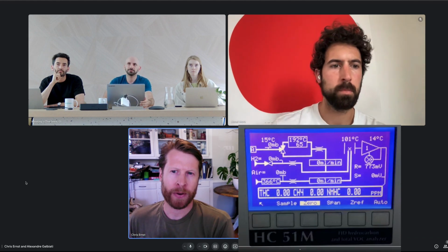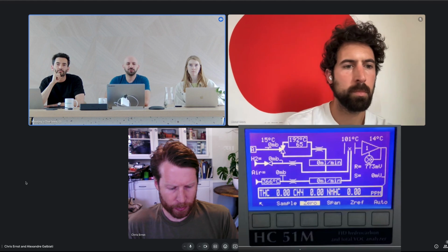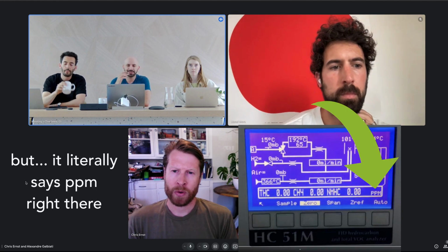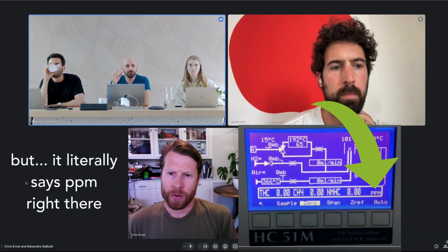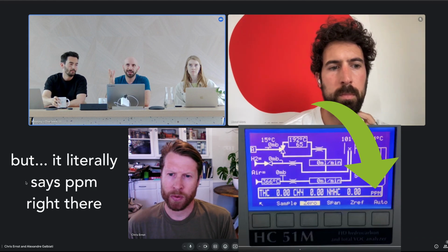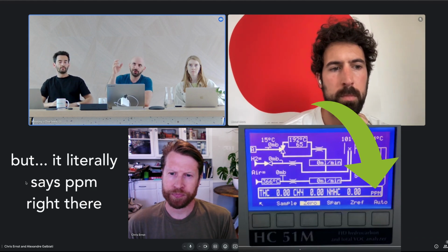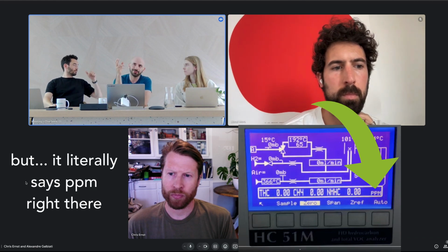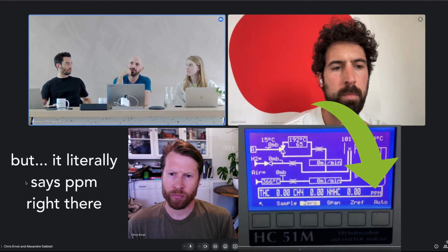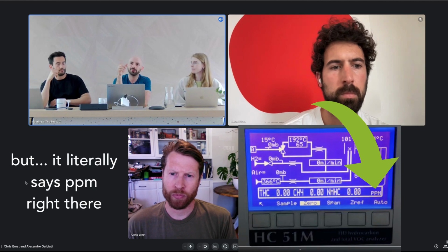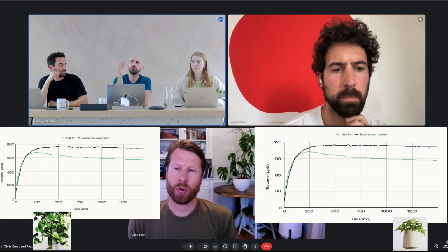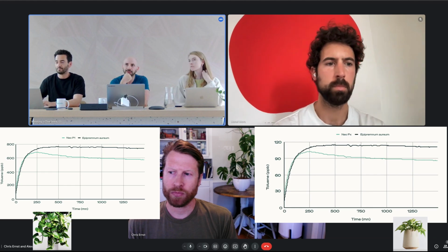Is that right? No, actually what it gives you is not really ppm values. The technique gives you the number of readings, and the number of readings can be either particles, parts, so toluene, or carbons, depending on how you set up the machines. And the machine was set up for number of carbon atoms and not number of molecules. So it's basically a normalization problem that we had.